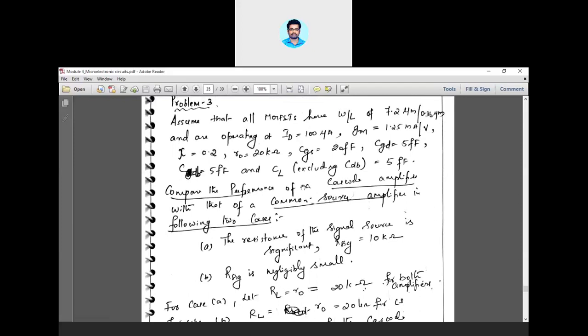You know that in a cascode amplifier, there are cases when you connect RSIG. RSIG is a signal resistance at the input terminals, and there are circuits where you won't connect RSIG. So there is quite a comparison between these two cases. If you have RSIG, it will lead to some other cases. If there is no RSIG, the gain bandwidth product of a cascode amplifier will always be a constant, provided RSIG should be equal to 0.